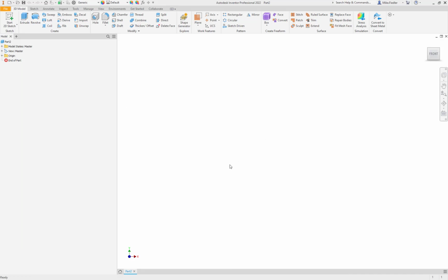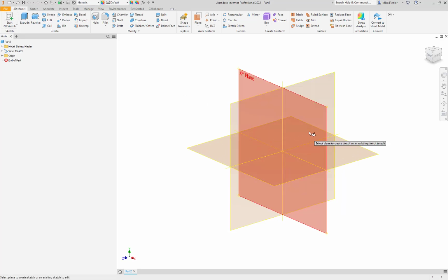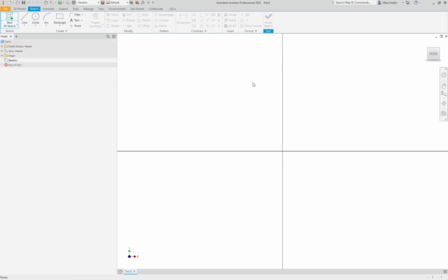So I've already inside of Inventor said that I'm going to create a new part. And to create a beam, there's a couple different ways that you can do it. Quite frequently, I'm starting from scratch, so I just create sketches. Just selecting a plane to draw on, I'm going to select the line command, and I'm going to start at the origin, go over a little bit, left click, and I'm going to draw another little line segment, left click again, then hit escape to drop it.